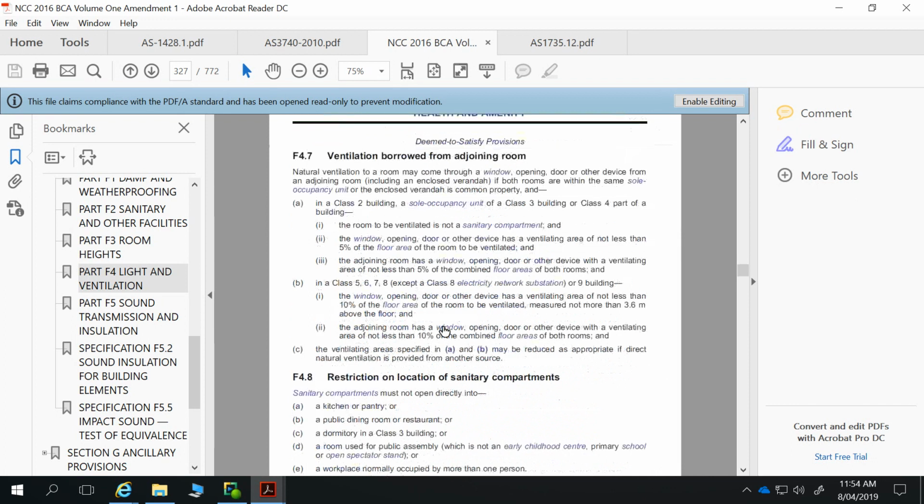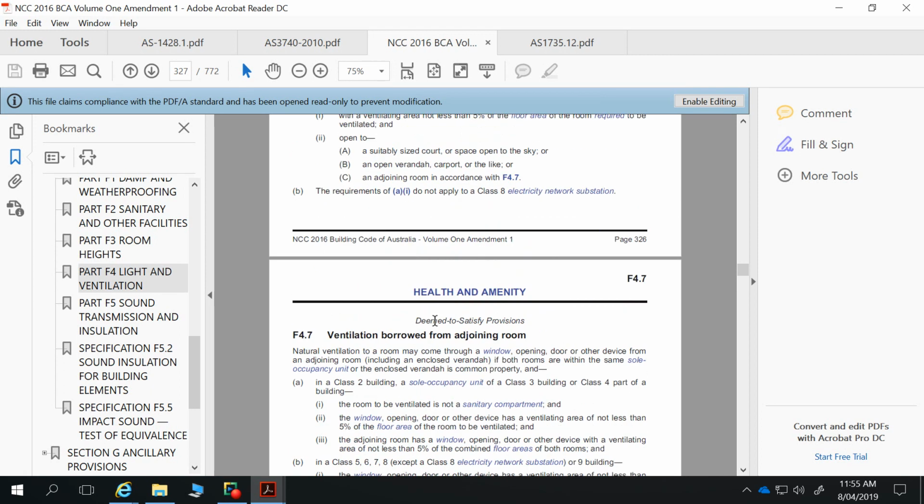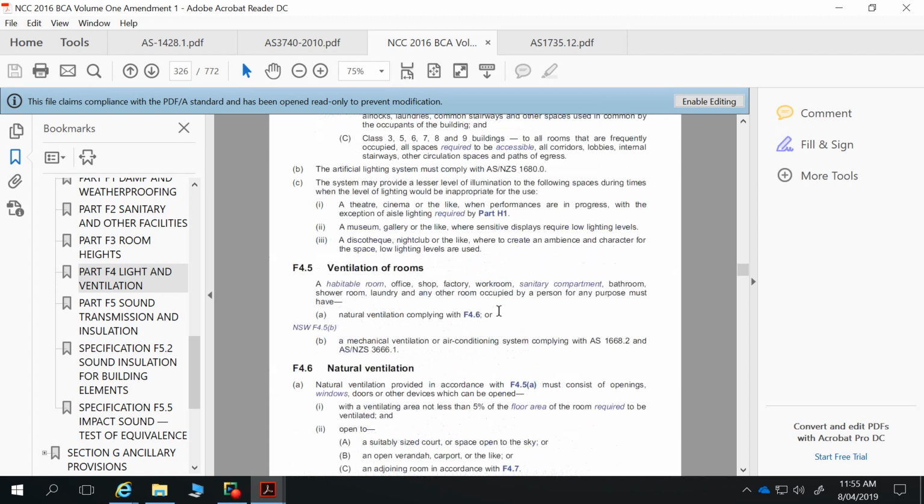So let's say you're doing an addition on an old bungalow, and that addition requires putting a room in front of a window which initially was the only light source for that room. The way you can go about that is producing double the size of windows on your addition to enable the penetration of light into that rear room. So if we go back up here to